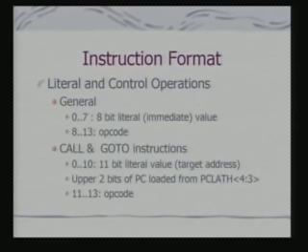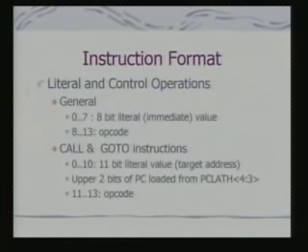So, the upper 2 bits come from the PC latch high register, where bits 3 and 4 are loaded for the upper 2 bits. Therefore, when you are making a call or goto, the most significant 2 bits are always specified through the PC latch register. This is a very interesting feature of the PIC instruction set, particularly the instructions which control program flow.